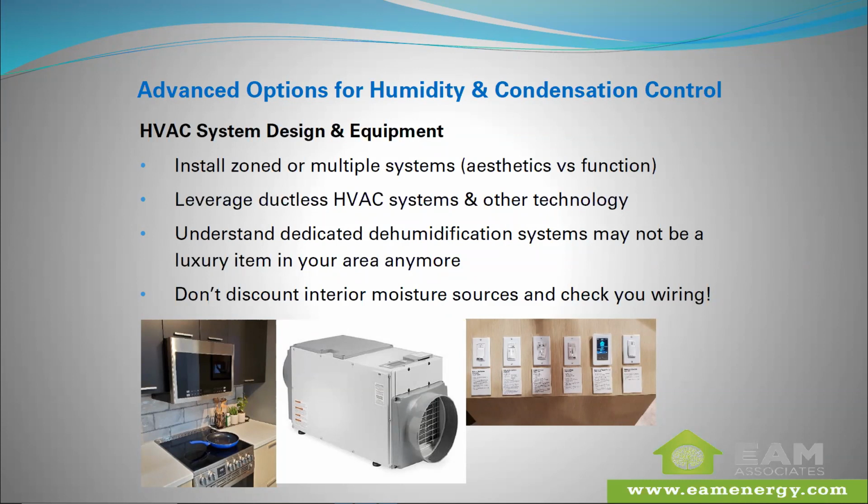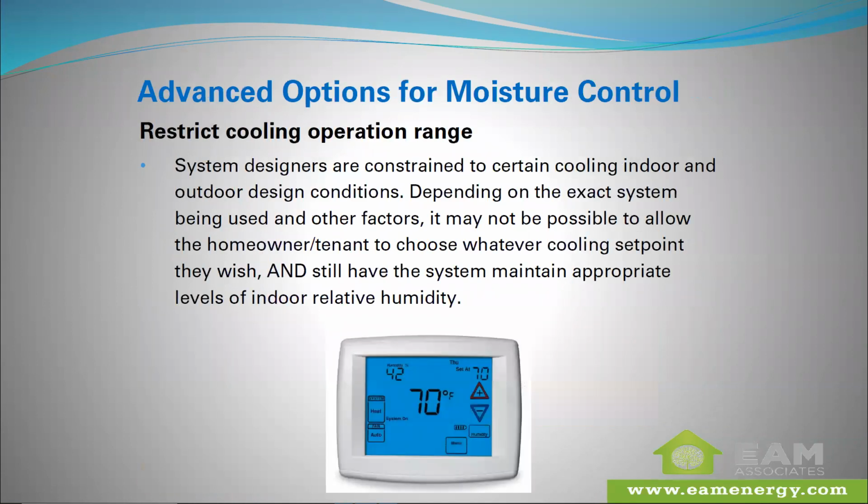On the right there is also a photo from IBS in Las Vegas, back when we were allowed to travel. Those are showing some options from Broan, just showing the wealth of options available for very specific combinations of different controls for your ventilation systems: occupancy sensors, humidity sensors, timer delays. So you really can find these solutions that are tailored to the needs of your project.